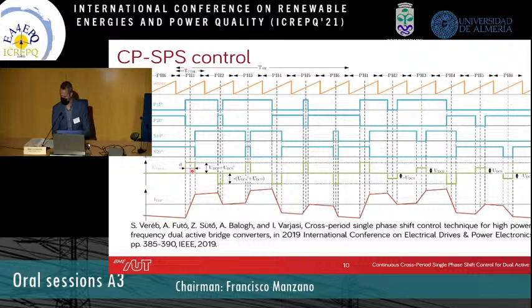Between these two switching actions, we can do various things to change the current without changing the magnetizing current. So this way the transformer sees 400 Hertz basically, but actually our control can run 3 times faster.